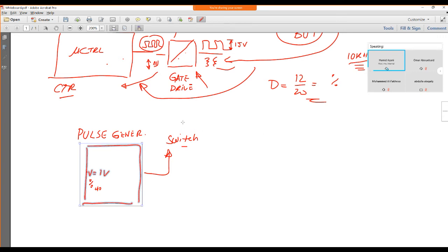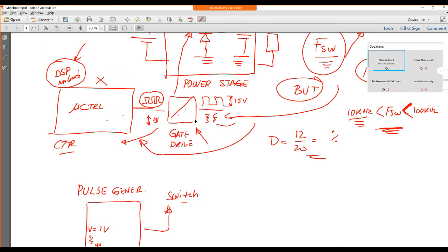You know how to find the switch in Simulink. You connect it there. If it's not working, be sure of the polarity of the switch. The plus of the DC should be connected to the collector, not the emitter, because the emitter will act like a block and no current will go there. The emitter will be connected to the rest of your circuit. The other leg will be connected to the pulses. This is for the switch, and that's for the duty cycle.